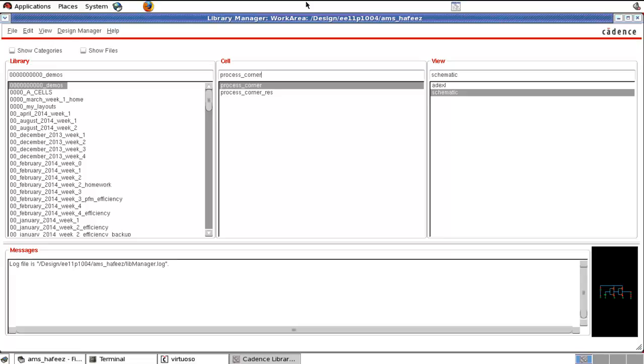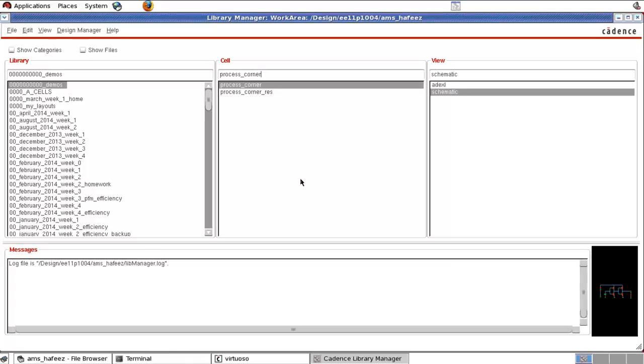This video will explain the parametric analysis in Cadence. Before watching this video, I prefer you to watch the tutorials on DC analysis and transient analysis. The parametric analysis is used to change a parameter and to repeat the simulation with that change in the parameter.